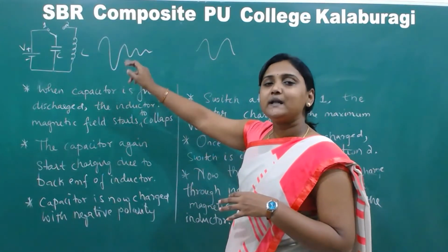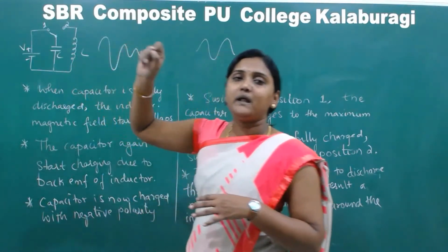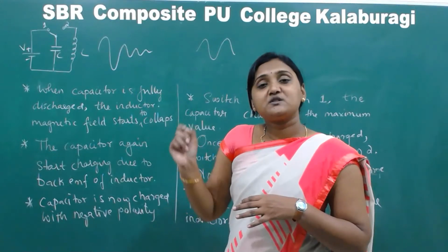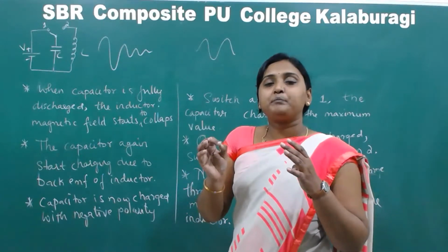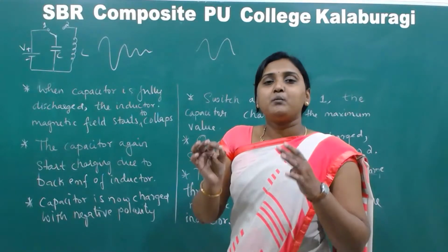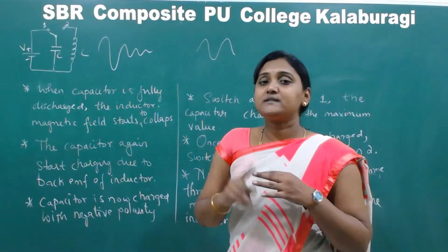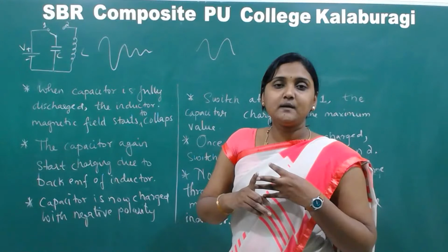We are not going to get an undamped output from a tank circuit alone. But along with the tank circuit, if an amplifier with positive feedback is used, it is going to act as an undamped signal generator, otherwise a proper oscillator, where it has to satisfy Barkhausen's criterion. What does Barkhausen's criterion say?